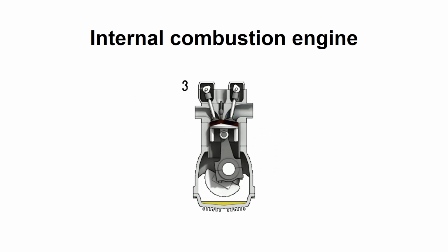An internal combustion engine could be of very different design. For most automotive purposes, the engine is a 4-stroke engine, which means that a complete cycle takes 2 revolutions of the crankshaft. The high temperature and high pressure gases produced by the combustion push down the pistons, thus creating work. The work is transformed into a rotating motion of the crankshaft, which is connected to the driveline and the wheels.